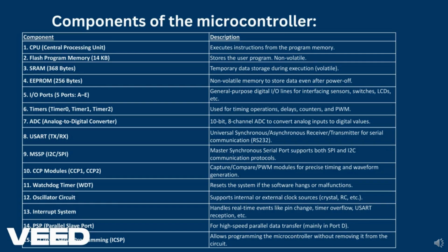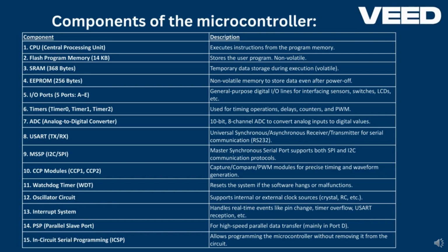And then I2C and SPI. The thing which differentiates USART from I2C is that I2C is very advanced compared to USART, which is a serial communication. Then followed by CCP modules. These modules are used where the function involves PWM, sinusoidal operations, PWM waves, and comparing the values. In all these cases, we use CCP modules.